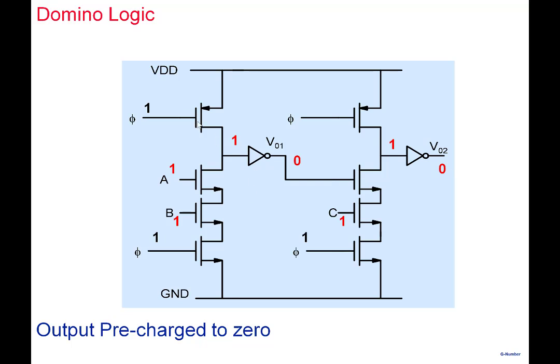So one is able to cascade this dynamic gate to the next gate here only if we add an inverter here. Otherwise, as I just showed you earlier, normal cascading, if you don't use an inverter, causes a problem. It may incorrectly turn on a transistor, cause an output to discharge, and give rise to an incorrect value here. So this dynamic gate that you see here with the inverter like this is what we call domino logic. Domino logic here, and so it goes fine properly here.